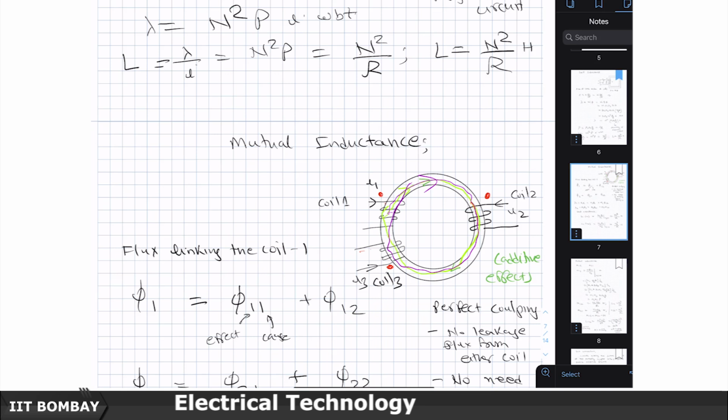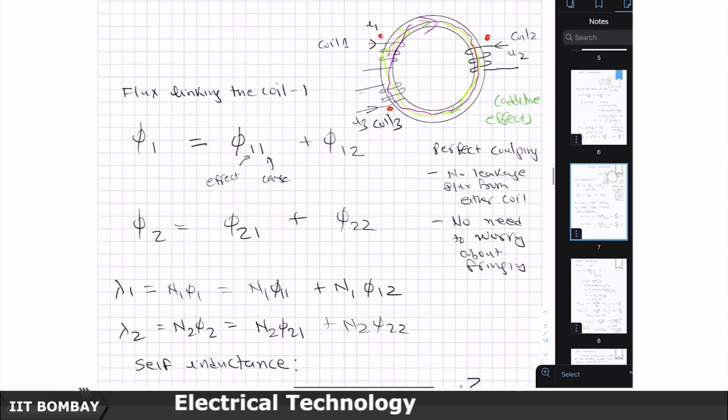No. Instead, even though it is put up as a black box, all the manufacturer, or the person doing the tests, has to do is do this check once and put the dots appropriately at the outside terminals. Then the end user can simply use it without trying to understand the geometry, the orientation, or the direction in which the winding has been wound.